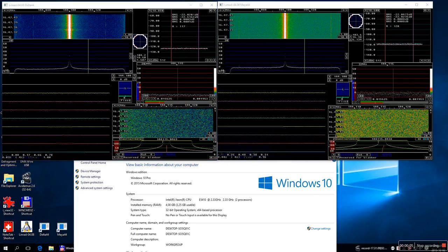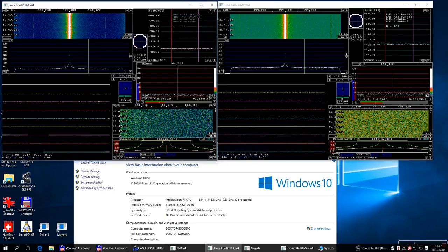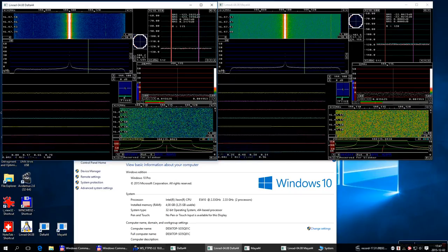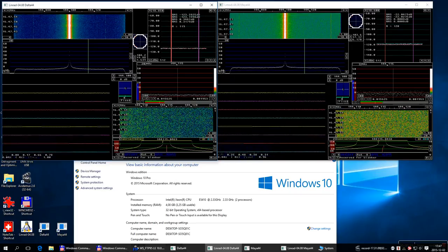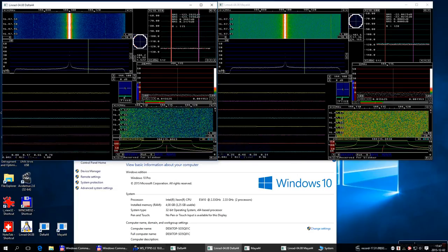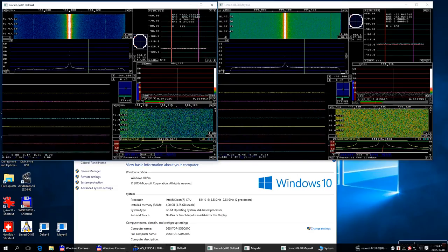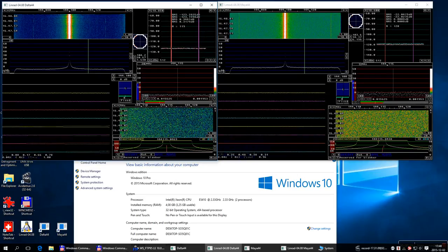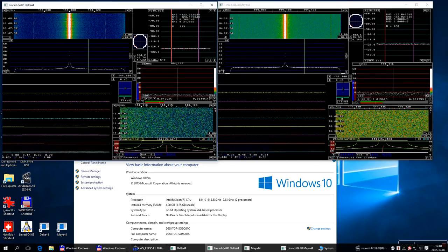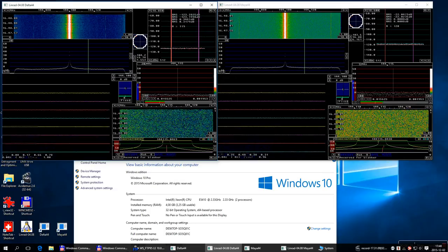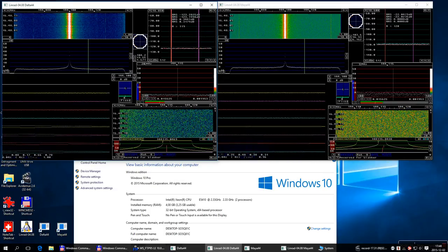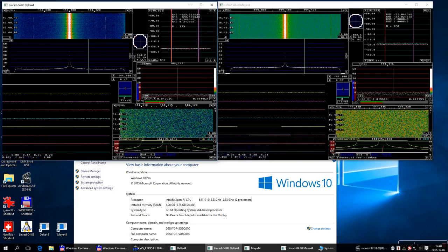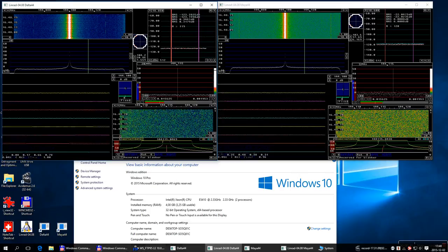The noise floor, we can see here, is minus 123 dBm in 10 kilohertz. That's minus 163 dBm per hertz, and that's 11 dB above room temperature, which is minus 174 dBm per hertz. So the noise figure with the Delta44 is 11 dB, 15 kilohertz from the center.